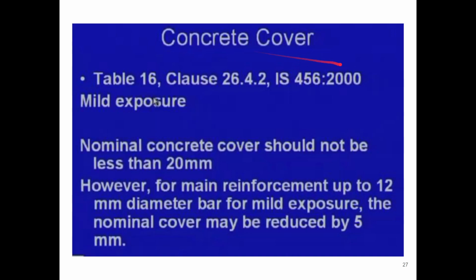And after that we have to consider the concrete cover. We have to find the clauses, the design guidelines which we have to adhere to for the concrete cover cases. How much concrete cover we have to apply, we have to follow this table, this clause and this code. That is mentioned in Table 16, clause 26.4.2, IS 456:2000.